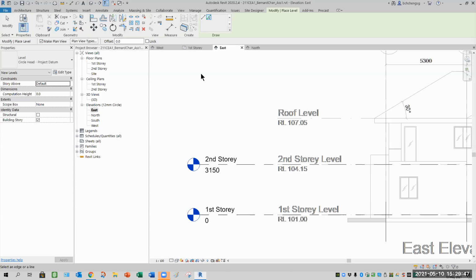Okay, no problem. Most important is your file. We are continuing your lesson, so make sure you save your project file. Now, while you are selecting the pick line, remember to generate the plan views. So it says make plan view, check.